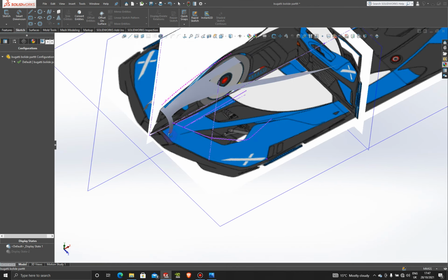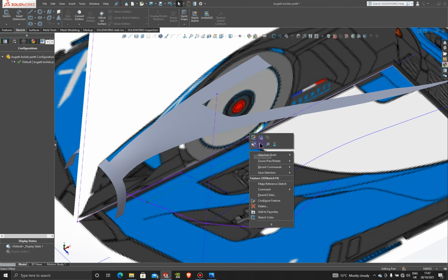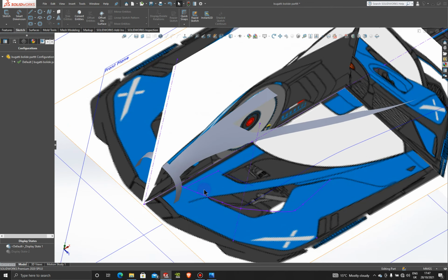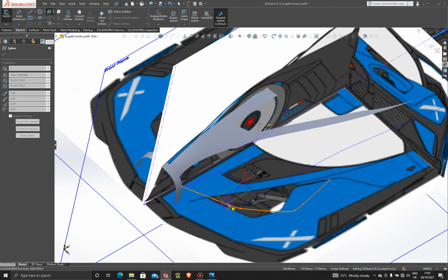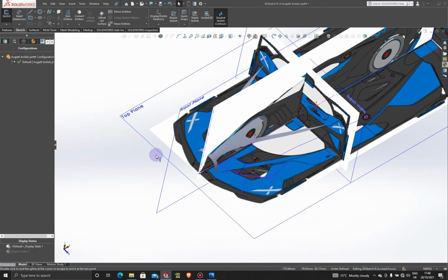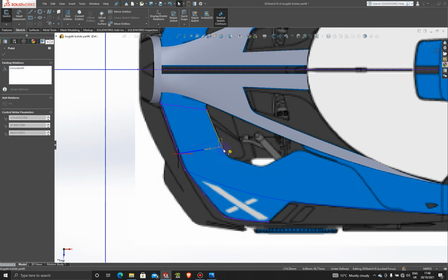And now we add our second line. Obviously, we can hide these lines now because we don't need them. Okay, and then we're going to add our second 3D spline. Add it from this line down to here. And let's jump onto the top. And we're going to pull this side all the way to the end. And on this side, we're going to pull it somewhere to that point. So that's where that curvature will start. It starts to curve up towards this way.